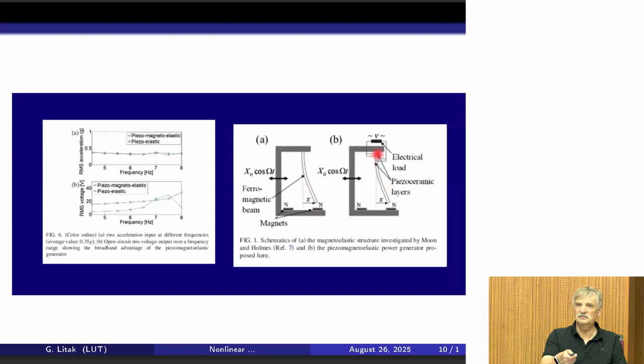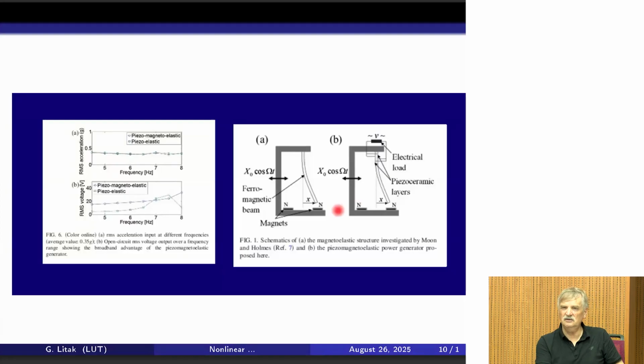The piezoelectric is placed at the beginning of the beam where it is clamped, because otherwise there would be some back effect, which is not good for us. If we have the piezoelectric along the whole beam, there would be a tendency to have the same curvature in every point of the beam, and this is some work which should be done in the mechanical structure.